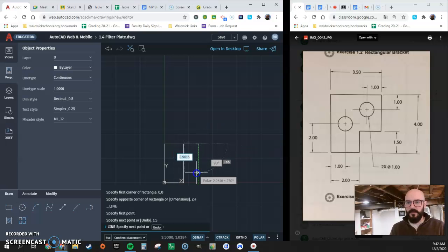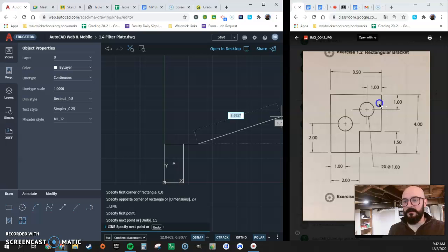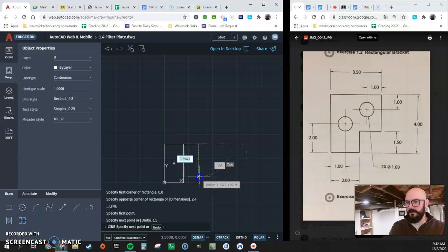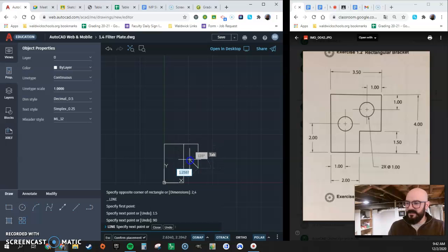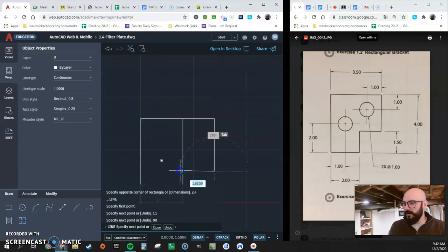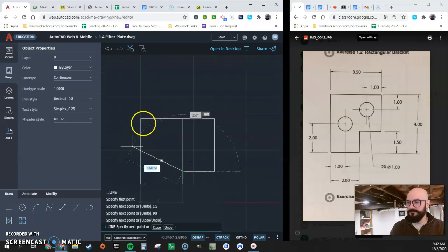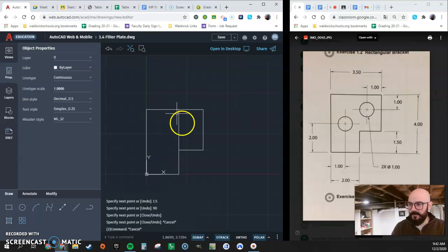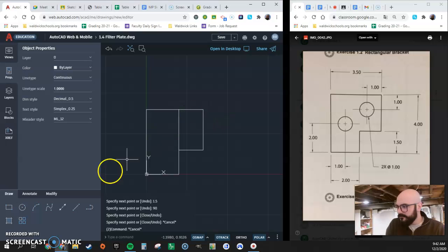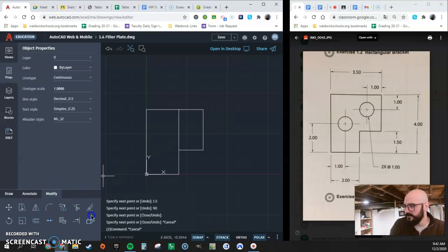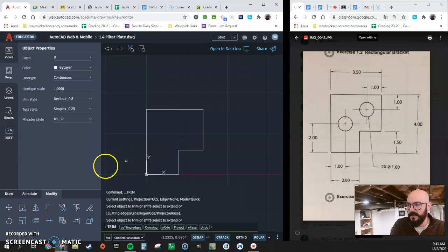I can now continue by drawing my line down. Now, it doesn't tell me the length of this section directly, but it tells me, okay, the entire thing's 4. This is 1.5. So, hey, let's do some subtraction. 2.5 plus 1.5 gives me 4. So 2.5, and I make sure that that angle is 90 degrees down. To switch the box, I press Tab. At this point, I can just do a perpendicular line that snaps to it. Now on my keyboard, I press Escape, and here I've got my outline. Now I can just use my Modify tool, Trim, boom, to clear that out.